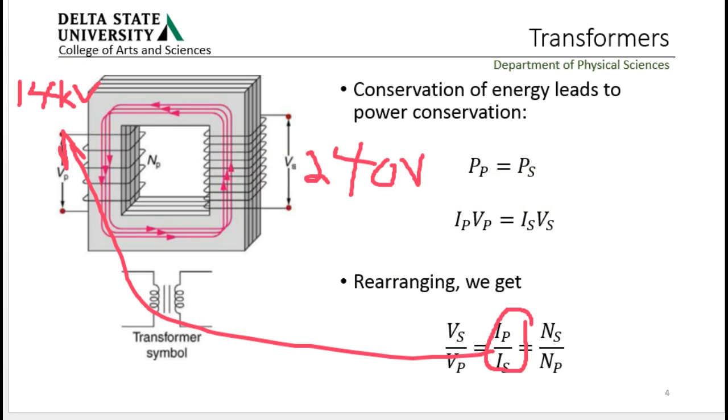Power dissipation in the line goes as I squared R, and since we can't get rid of the resistance of the line, if we minimize I squared, we cut down on the amount of energy that gets lost in the transmission lines carrying power to your house.